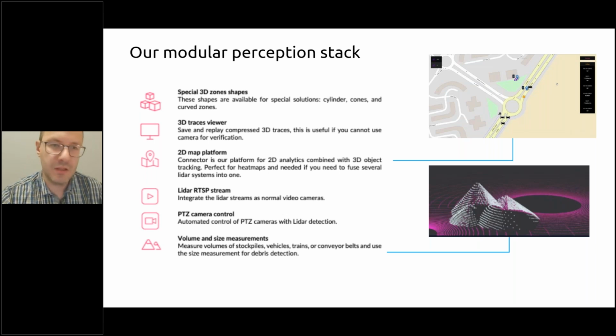At the same time, it can provide converted information about objects with GPS coordinates instead of LiDAR coordinates. So you can even calibrate such a system indoors and get GPS coordinates of objects which are moving indoors based on the LiDAR data, whereas GPS itself would not be possible to get perception in such places.